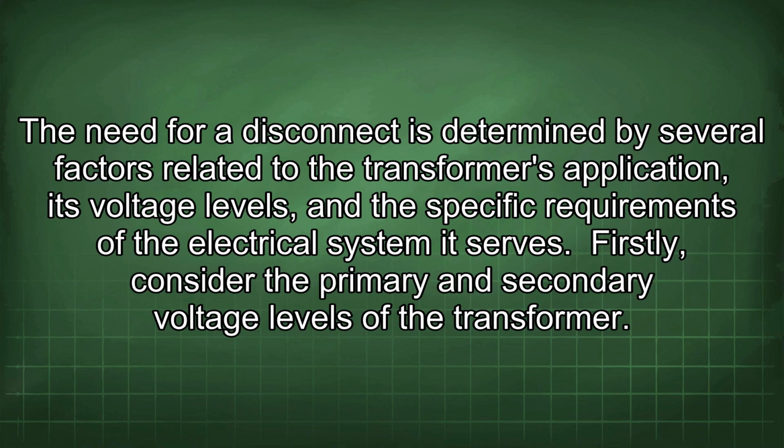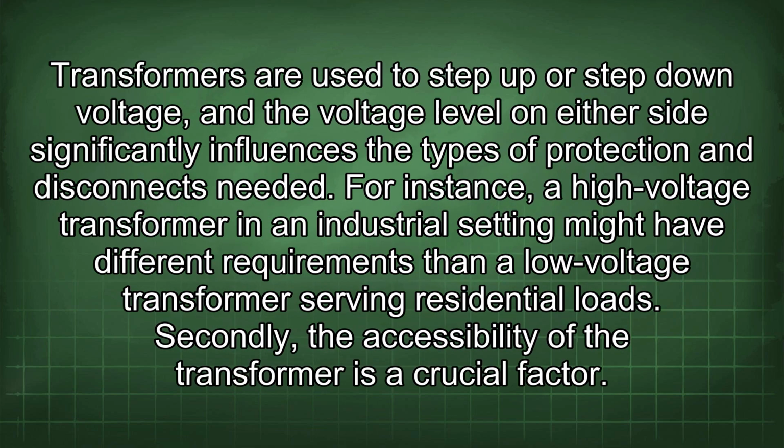Firstly, consider the primary and secondary voltage levels of the transformer. Transformers are used to step up or step down voltage, and the voltage level on either side significantly influences the types of protection and disconnects needed. For instance, a high-voltage transformer in an industrial setting might have different requirements than a low-voltage transformer serving residential loads.